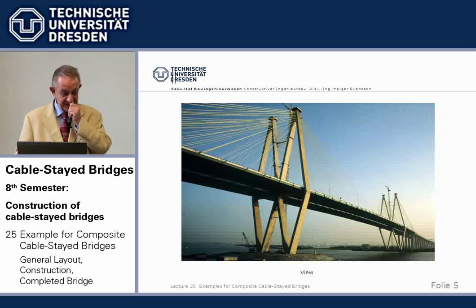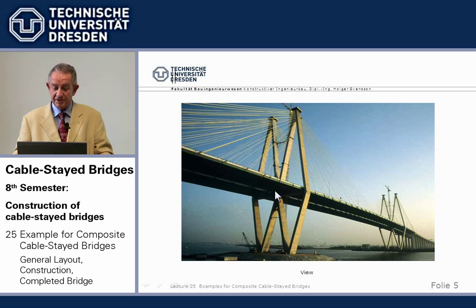towers then were a consequence of these 2 beams. We wanted 8 towers above deck for each beam for improved torsional stiffness. I told you about that. And then if we connect the two, we can also take the legs together to have only 2 foundations.